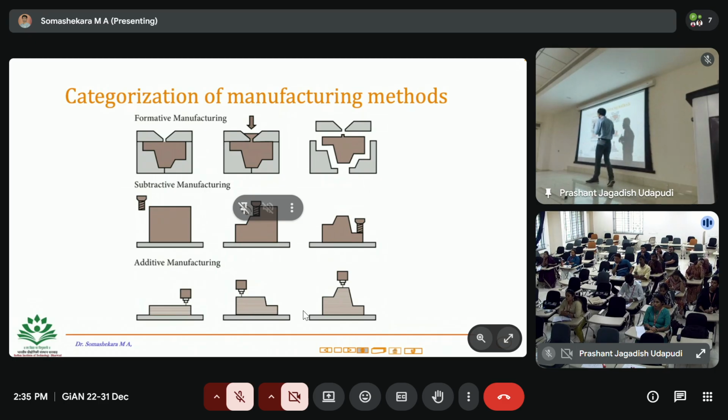But then as you start building it up, as you start using it, and then you start comparing many things with the traditional manufacturing processes, in terms of properties, in terms of surface finishing, right? For example, when you get the 3D printed part, you quickly realize I am getting better surface finishing when I go for subtractive manufacturing.